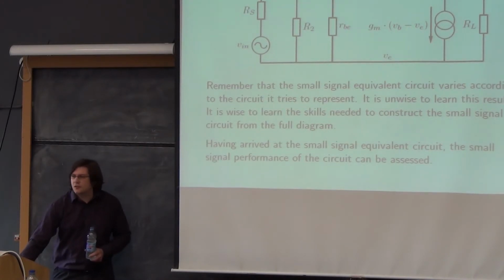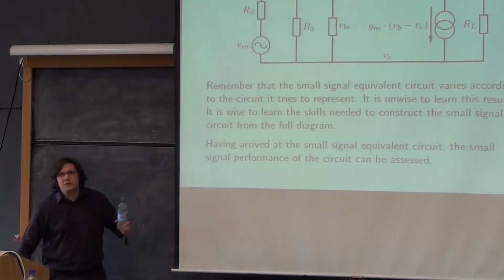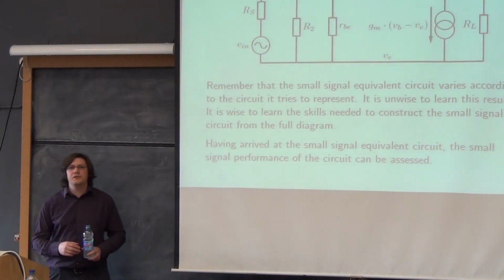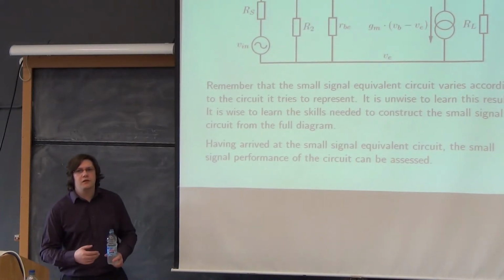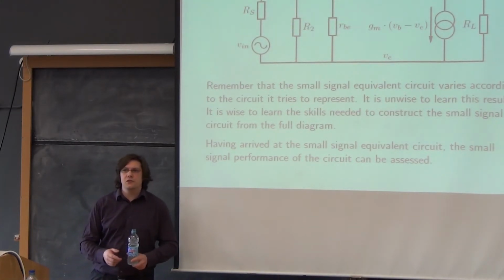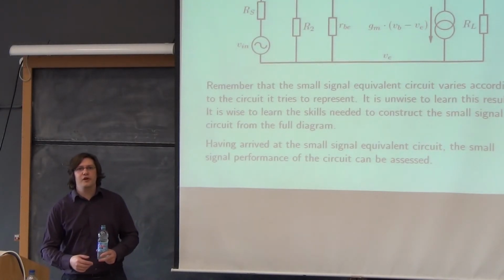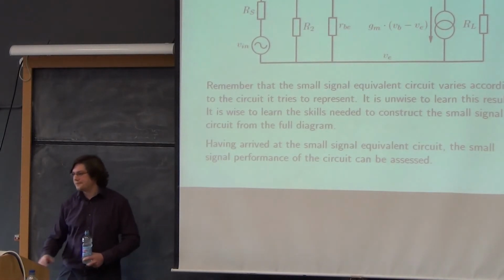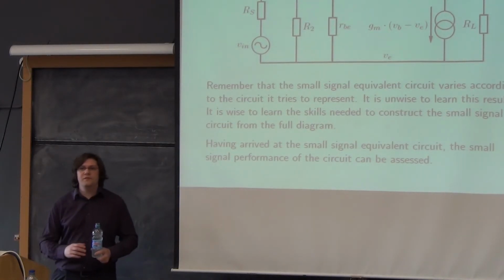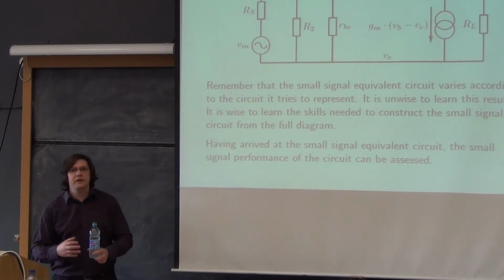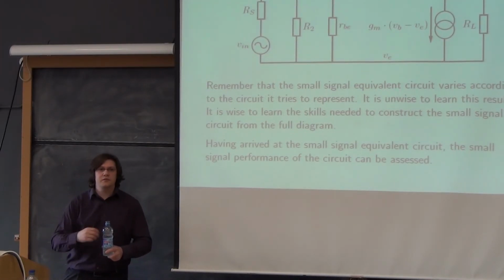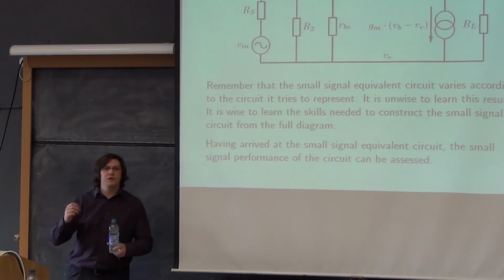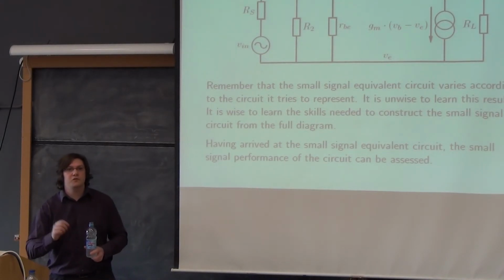all of the components in this circuit are linear. That is to say, they all obey relationships between voltage and current which are not exponential or square law or logarithms or anything funny. It's all Ohm's law. In fact, it's all Ohm's law. And that's important because what we've secretly done without saying so is linearised the circuit. That's to say we've removed all the exponentials and whatnot and replaced them with a straight line version based on the point on which we were at the exponential.